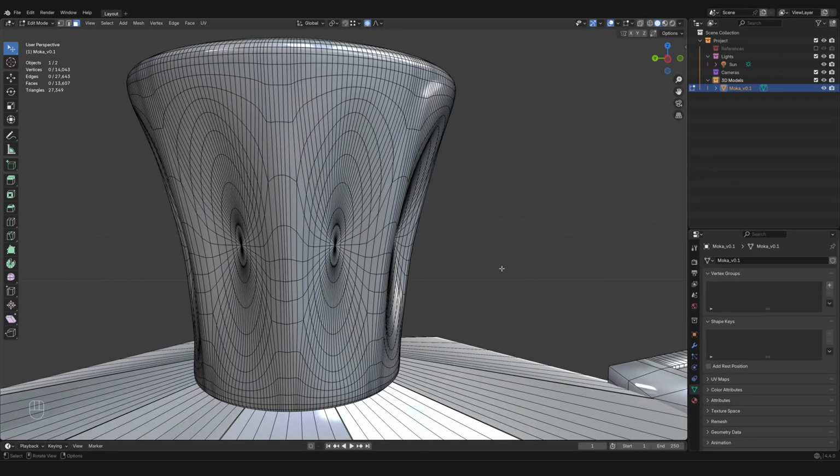Okay, moving on, we are discussing the dissolve technique. The dissolve technique allows you to select something, which could be one edge or an entire edge loop. And then when you press X, the delete menu comes up and you can dissolve either the vertices, edges, or faces. The one I use most frequently is dissolve edges.